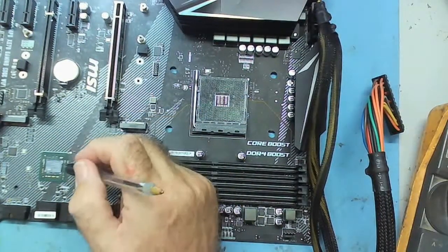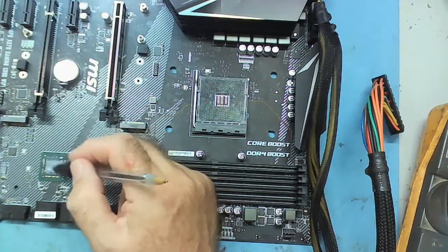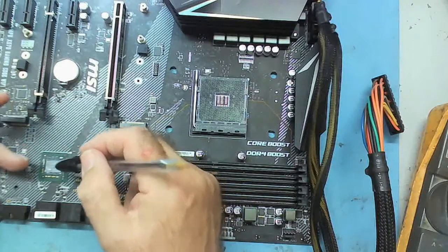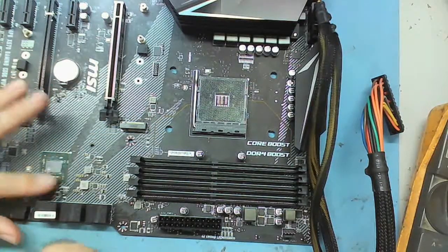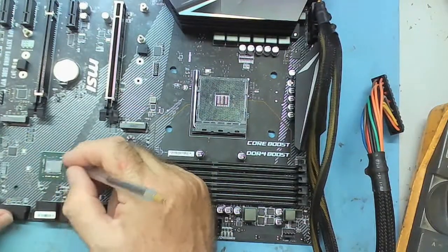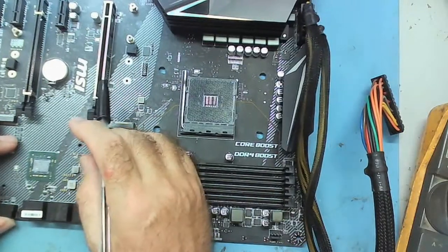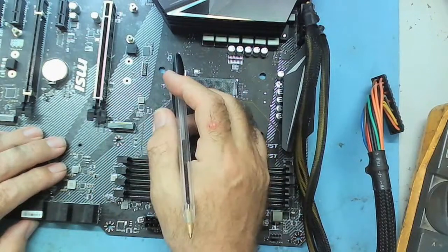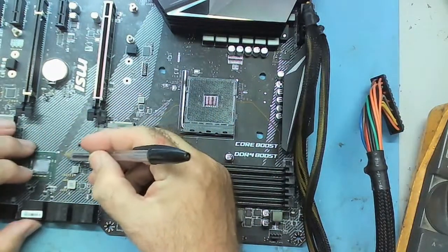Right. First thing you could do is look up the datasheet for this chip and see if you can find the datasheet, and in the datasheet it should tell you what the power rail voltage should be. So if you can find the datasheet for that, you can look it up that way, yeah? But something like this chip, Northbridge, you might not, depends the age of it. So let's say you're unlucky and you can't find a datasheet for that, yeah? Can you still determine if the voltages are wrong? Yeah, you can.